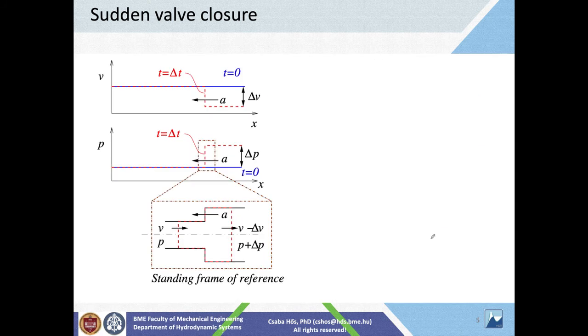So now we open the fluid mechanics textbooks and use the control volume concept. Along the shock wave, you get a control volume. This is the pipe. To the left of the shock wave, nothing happened yet, so you have the usual diameter, and velocity and pressure are the undisturbed values. Whereas to the right of the shock wave, you have an expansion of the pipe because of the larger pressure, so the pipe diameter is larger and the velocity is smaller.